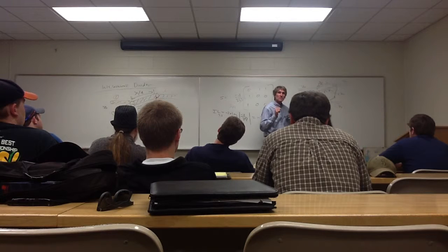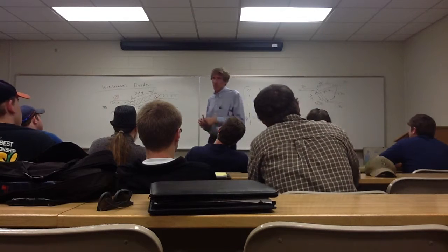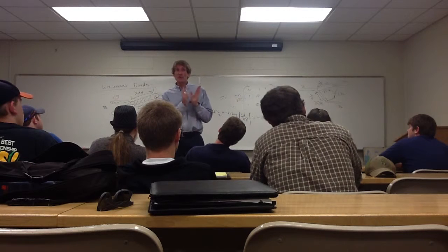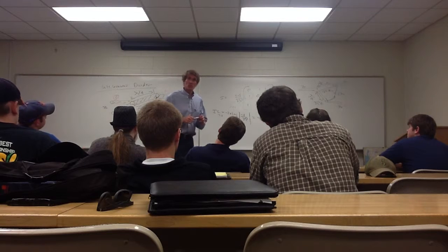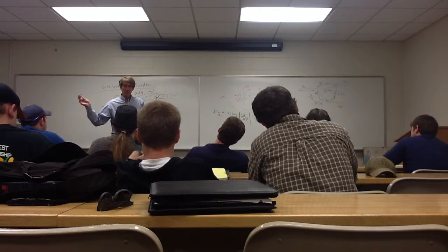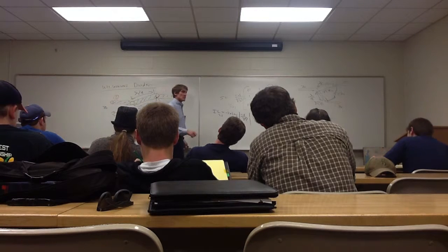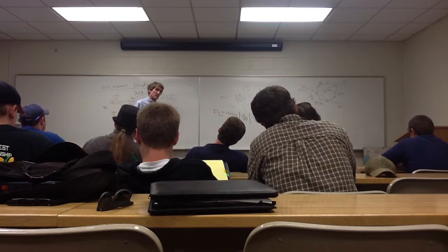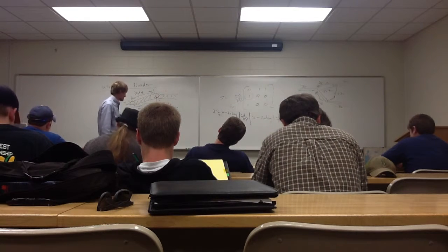So a Wilkinson divider, another downside of it, even though it's a little more difficult to fabricate, it works on a very narrow frequency range. Keep that in mind. Those are the two things. The resistive divider is wideband. You can use it at any frequency. Does everybody see that? I know this seems kind of dry until you get some threatening problems that make you think. But it is necessary that you know this.